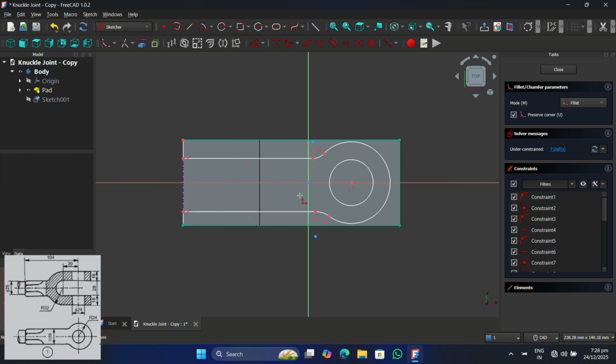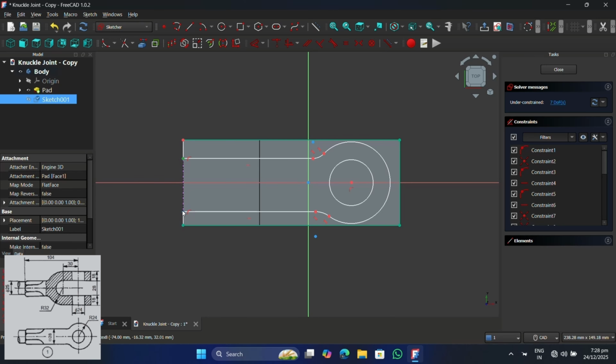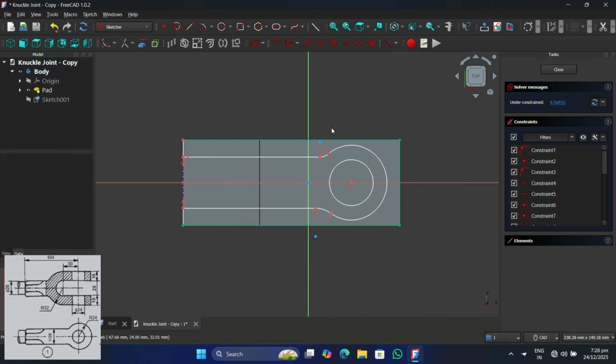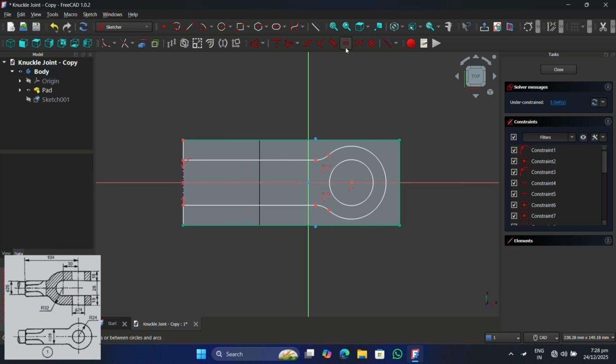Apply geometric constraints and dimensions to the sketch to make it fully defined. Make these 2 points symmetric about the x-axis. Make these 2 arcs the same in length by applying the equal constraint. Apply the proper dimensions as shown in the figure.